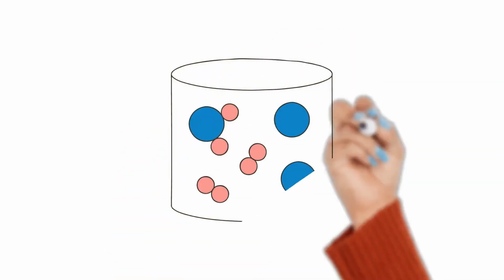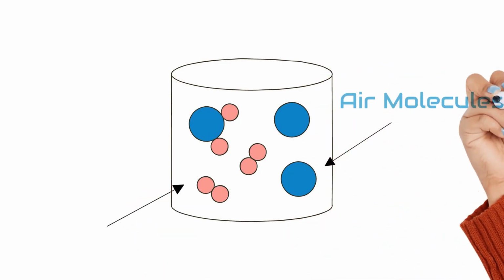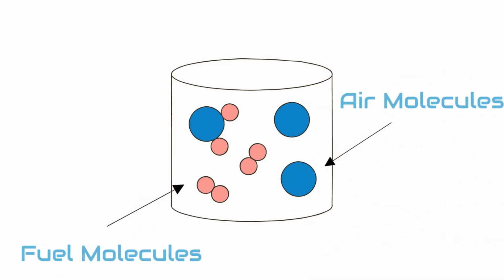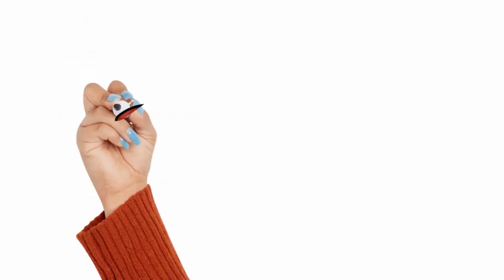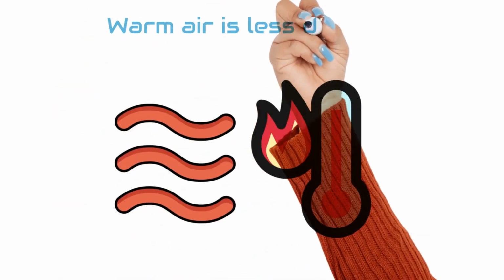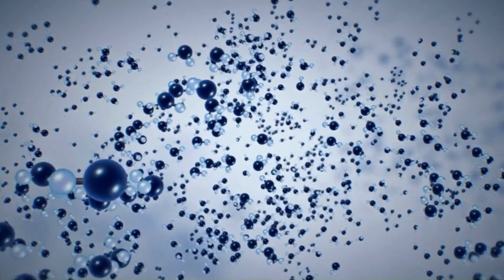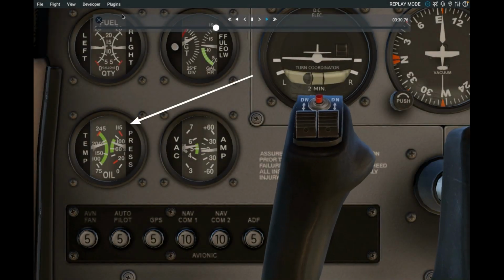Fuel-air mixture is the ratio between the mass of air and the mass of fuel, the mixture prepared for combustion at any given moment. Carburetor heat enriches the fuel-air mixture because the air is warm, and therefore less dense. The fuel-air mixture becomes richer since there is less air for the same amount of fuel. Applying carb heat decreases engine output and increases operating temperature.